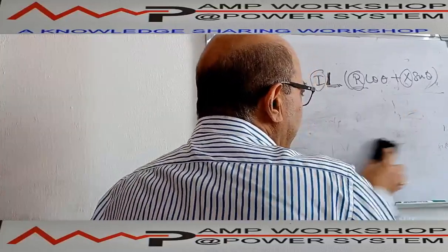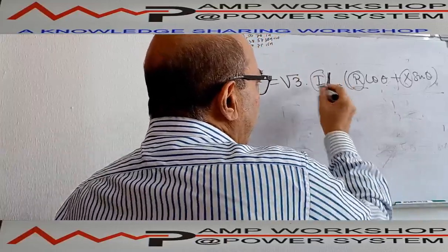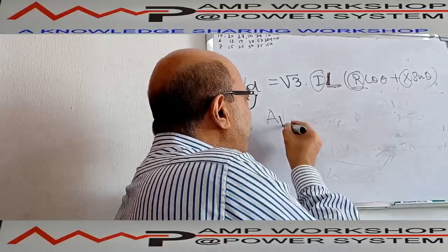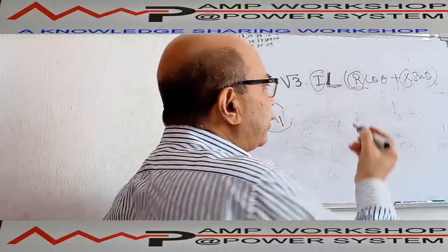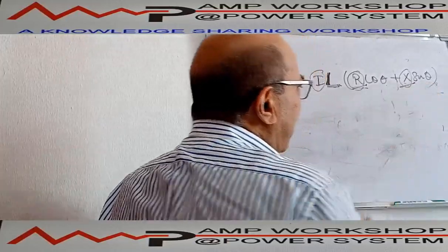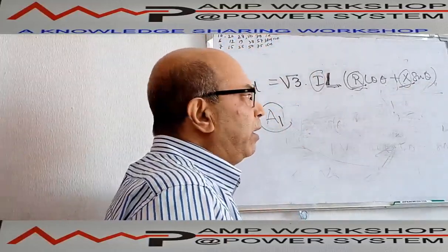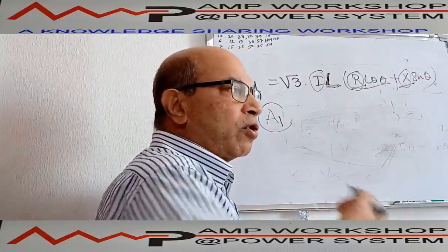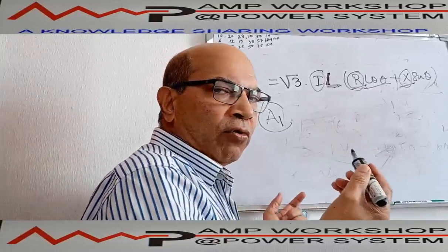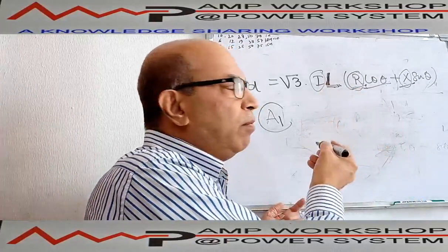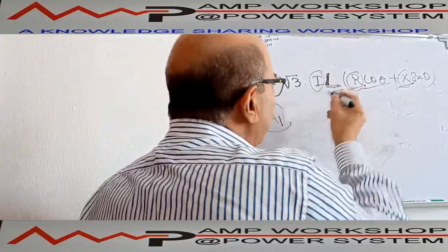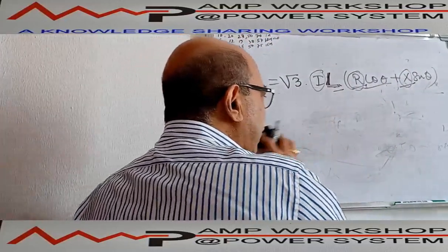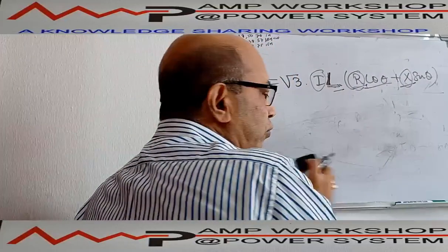current of the cable, how much current it is carrying, that is the current I, and we have already the size of the conductor. Conductor size, we already got the conductor size A1, and from the cable manufacturer table we can get the R and X per unit length, per meter or per foot as per the table. How much resistance, how much reactance. We know the power factor of the load. Suppose with the motor, the power factor is already on the nameplate. We have considered the power factor in calculation of the full load current. So this factor we know. From this we can calculate the voltage drop. Once we get the voltage drop, then we can check whether the voltage drop is acceptable to us or not.